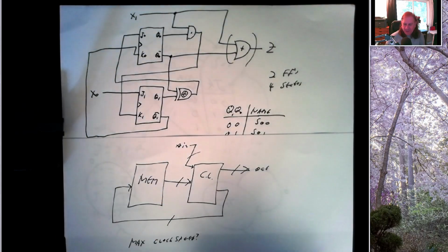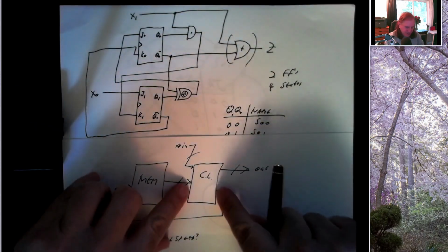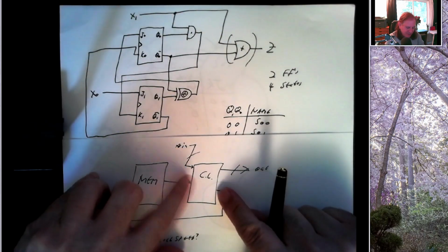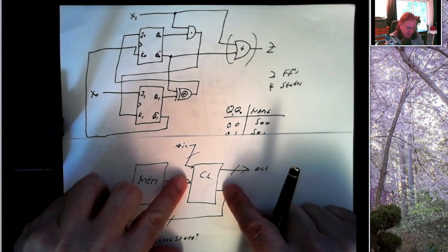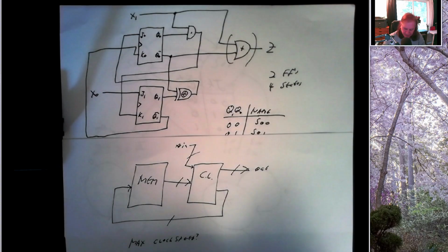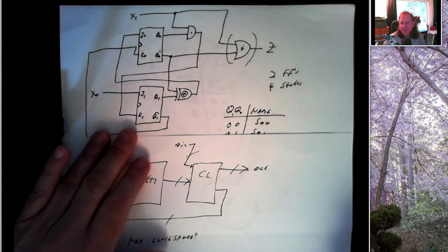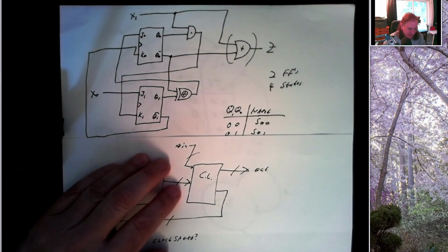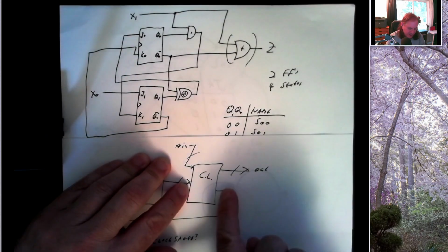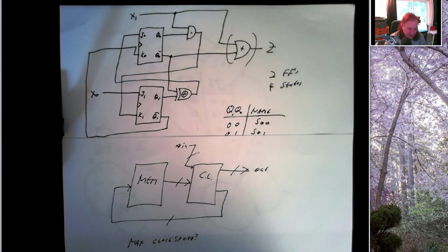If you do this with software tools, one thing it will tell you is the worst case propagation delay from an input change to an output, and it'll come up with some figure for you, and it's going to be an over approximation, because if you come up with a number that's higher than reality, that's okay. But if it might take 20 nanoseconds to come through this circuit and you decide the worst case is 15, then you've got a design problem.